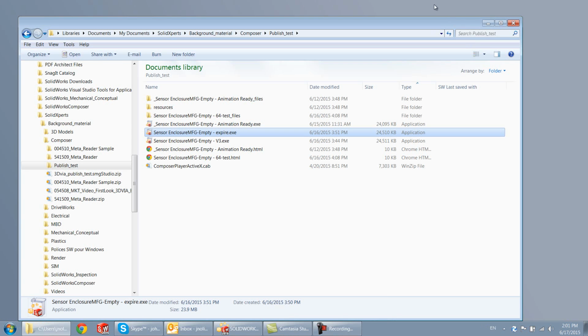Again, this has been a quick technical tip just to highlight the package option and what it actually does for you. I think it's a nice way of making an archive or a self-viewing file that you can give to a manager or somebody else that you're working with, perhaps a customer, even a user in another division who may not have the same applications you have installed. So long as they have Windows, this will work. It's a self-running exe. It doesn't need to install. It just pops up and runs.